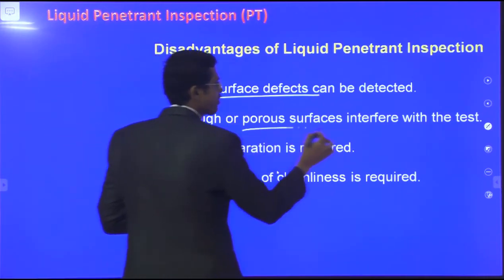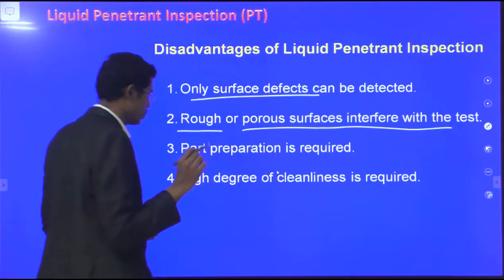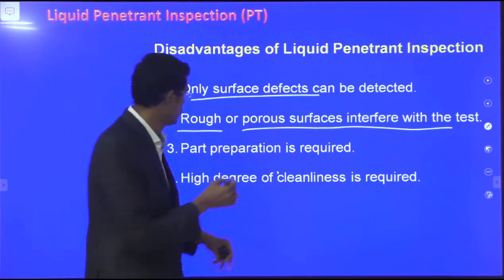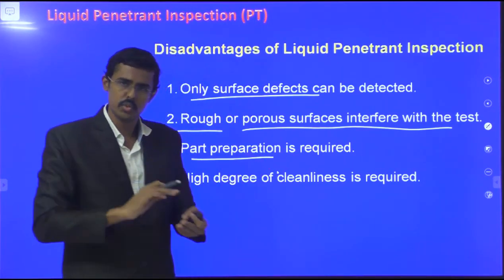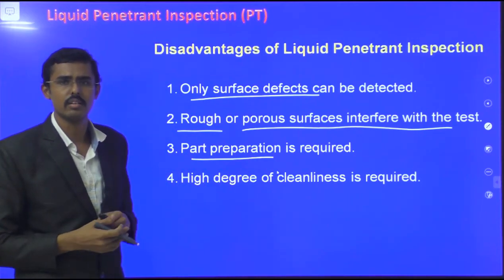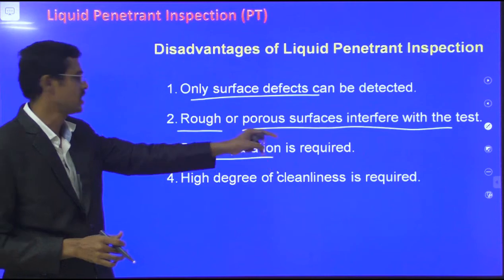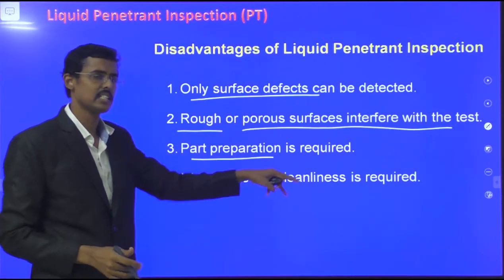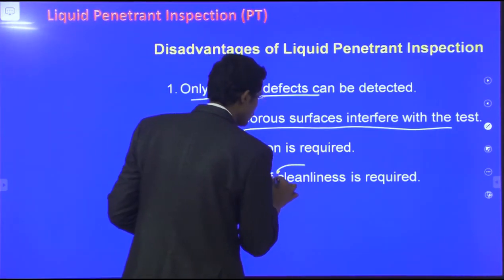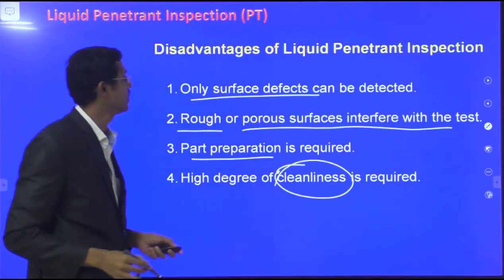Rough or porous surfaces interfere with the test, so it is not possible. Part preparation is required. What is the part preparation? We should clean before applying the penetrant and before applying the developer. So these steps are needed. A high degree of cleanliness is required.